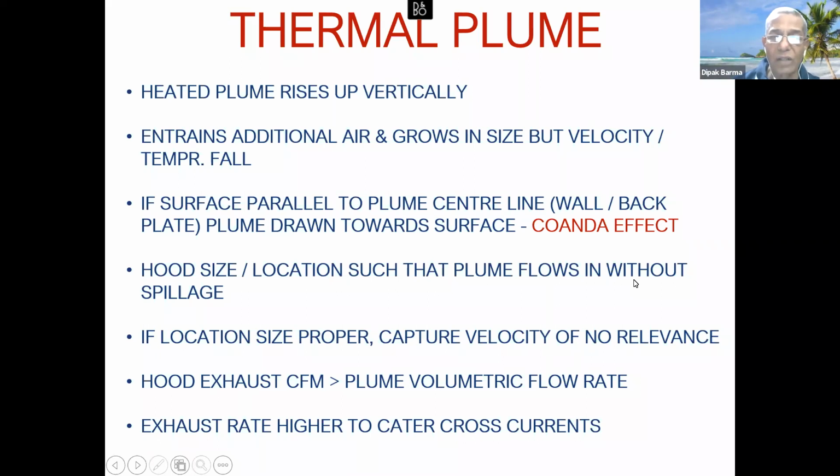Now the hood size and the location must be such that the plume flows in without spillage. We do not want this plume to be spilling out of the hood, and that is why the design has to be perfect, the exhaust air arrangement has to be perfect, so that the entire plume is captured and contained within the hood and exhausted out.